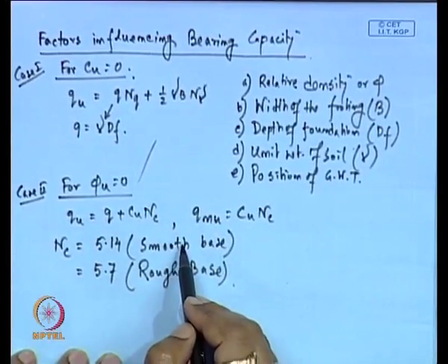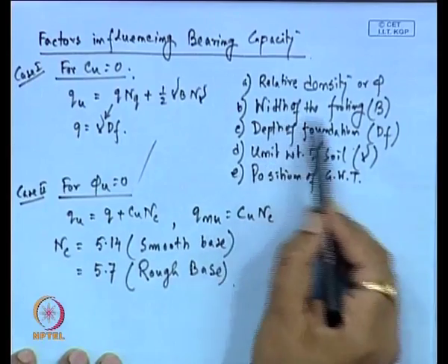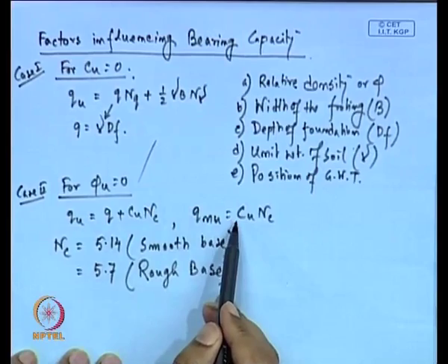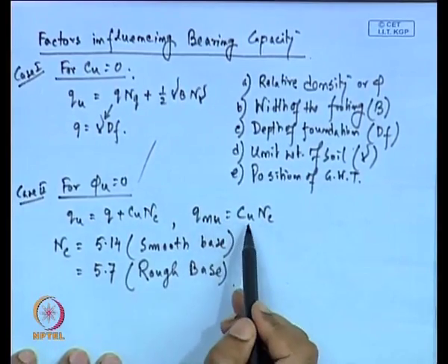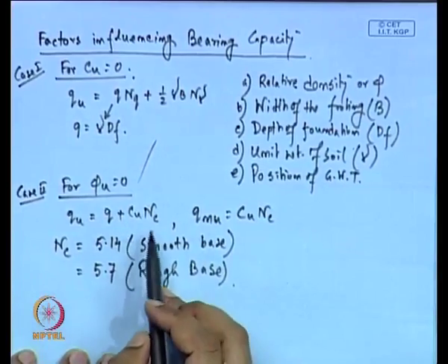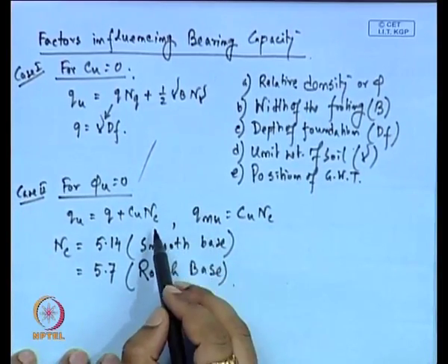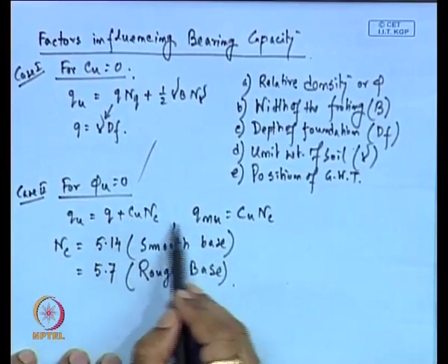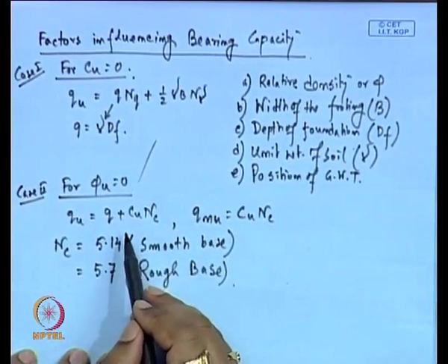bearing capacity. Now, the second one is the width of the footing. From these two expressions we can say that the width of the footing is not influencing the bearing capacity of the foundation if it is resting on clay soil, because here the B term is not present.